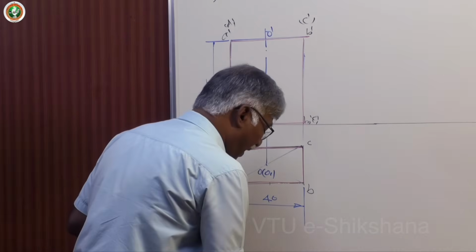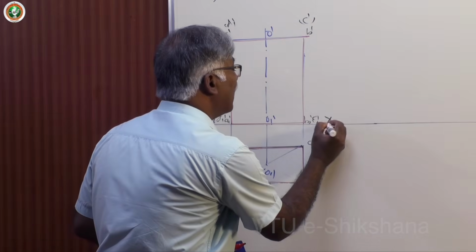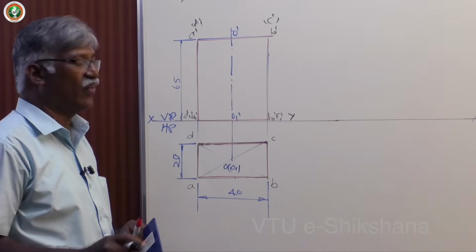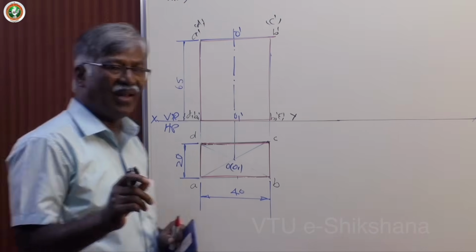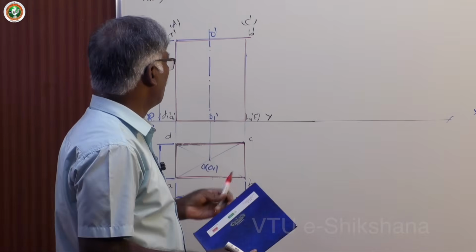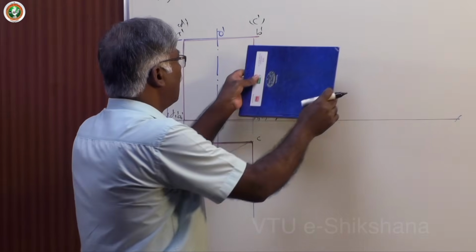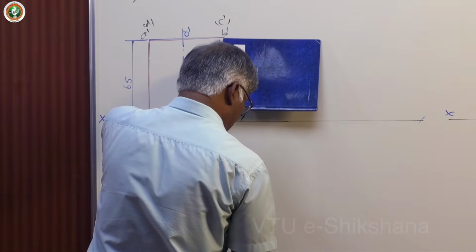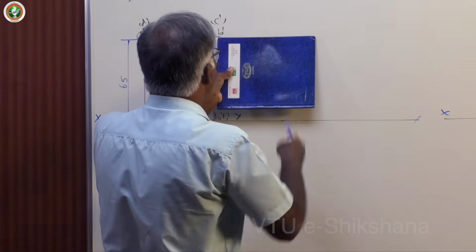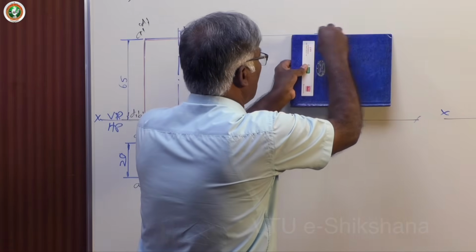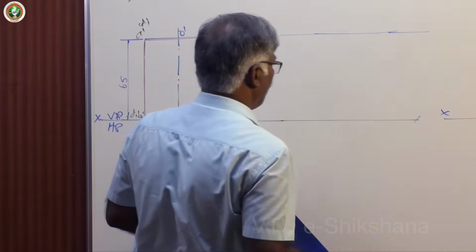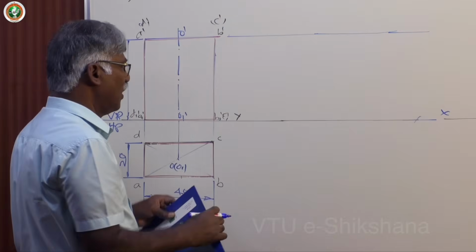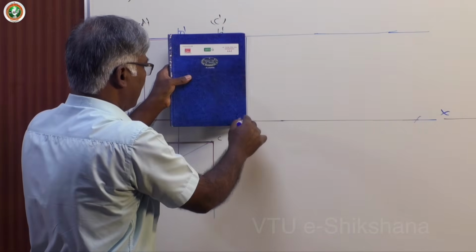Here we have X, Y. Let me end Y here only, and this is the portion for development. Parallel line method for all cylinders, prisms. Parallel line method is the best method, and it's the only method we use. Draw parallel lines. So this is not part of the XY line, this is an extended line. Now start with a vertical line.